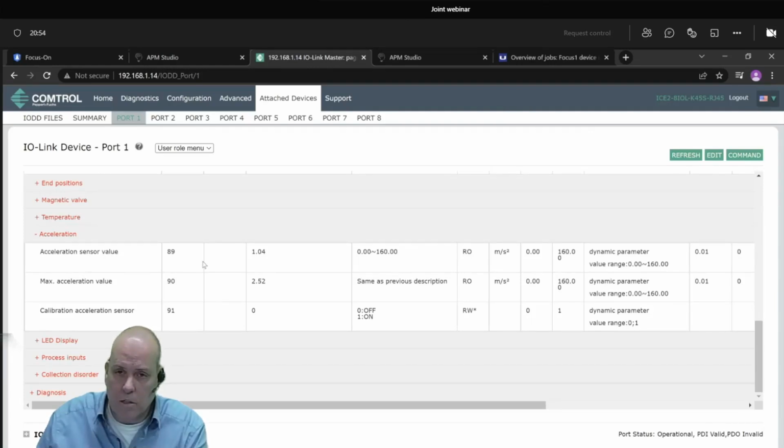In this case, next to the remote I/O gateway there's actually also an IO-Link interface. And there we get acceleration data directly from the flow loop, which is relative to a number of sensors that have been placed near rotating equipment. Again, here it's raw data. You need to process this raw data in order to make sense of it.